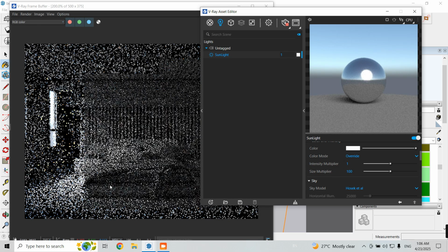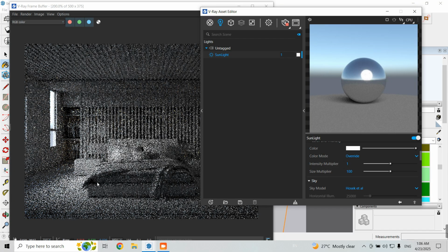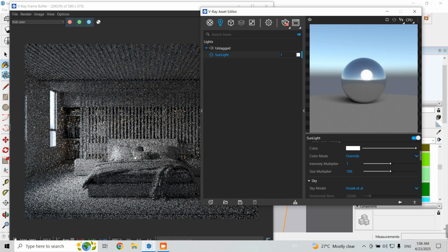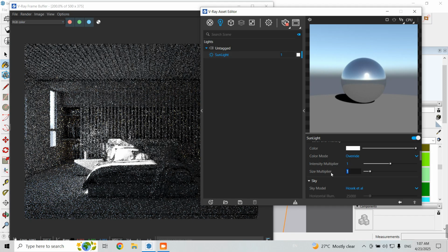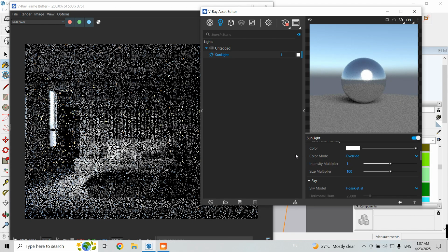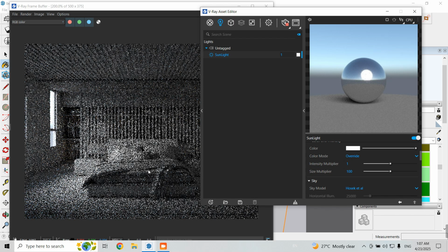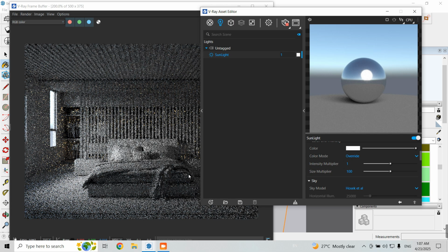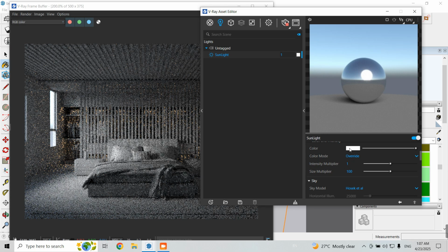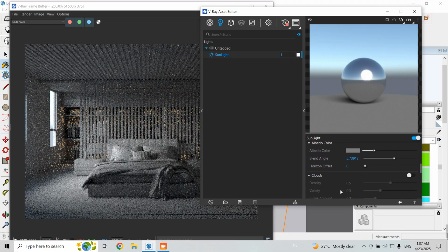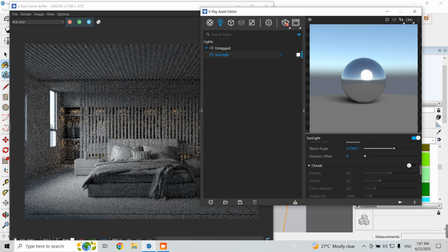So when I make it 100, you do not see any shadow, sharper shadow becomes softer. If you make it to one, you can see the sharper shadow. Okay, now I want the softer. Okay, now this one, because the overcast means you didn't really see the sunlight. Okay, this is what overcast means. So intensity I will make it default to 1. And then you can add the clouds if you rarely see from the sky.